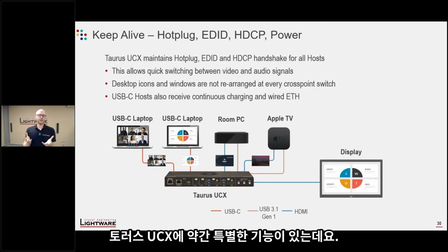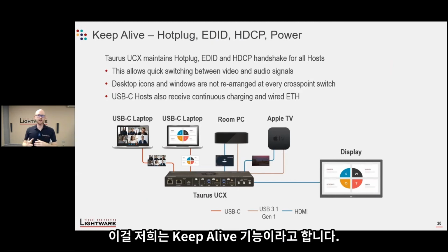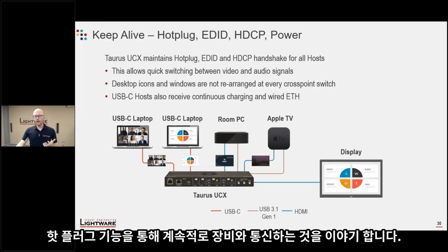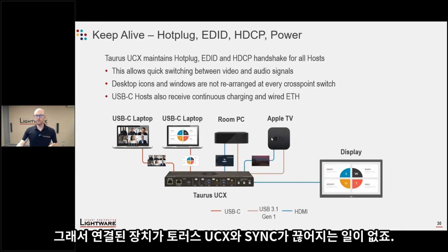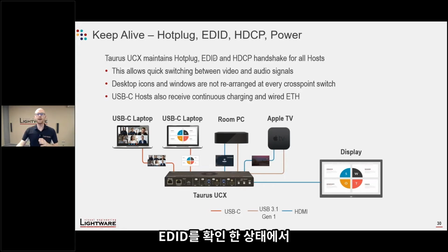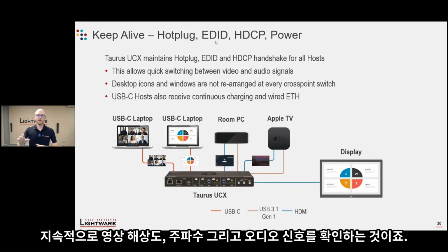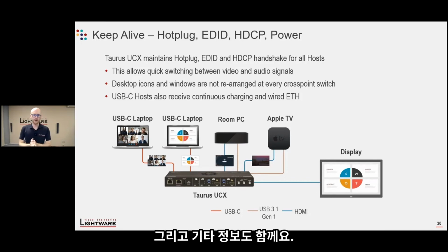There's a collection of features or functionalities which we call Keep Alive. So firstly, hot plug is maintained for all of the source devices, so they don't lose sync with Taurus UCX. A hot plug is always there, which means they have read the EDID, they are all set up, they are sending video at the required resolution and refresh rate and audio at the desired format.